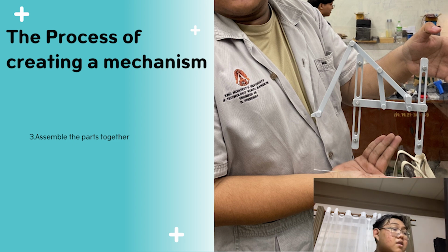For the base support on the acrylic sheet, we will create locking points by drilling holes in the part and using a screw to secure them through the component and the acrylic sheet, locking them in place with an M5 screw and M5 stud. Finally, we will connect the base support and the linkage together by using a pin to drive into both components, and then finally we will have the linkage.